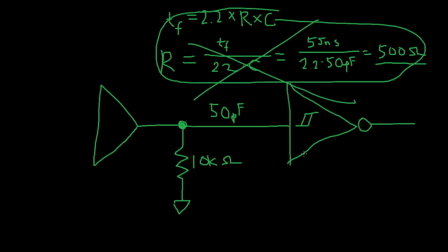Essentially, your Schmitt trigger device is just going to have some hysteresis added on the input, and it's going to allow for very slow transitions without ever oscillating, and the amount of power drawn will be far less because the input is designed to have those slow input transitions.